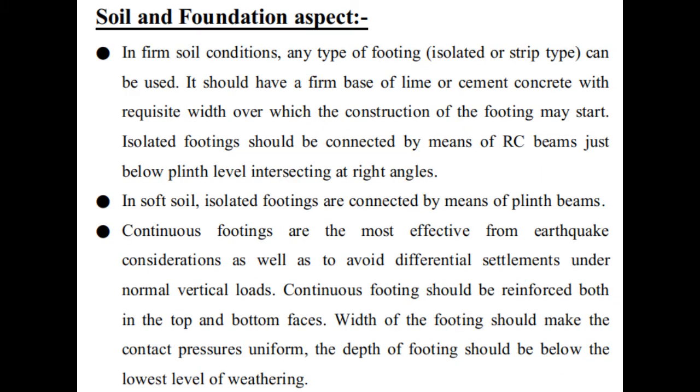Let us now see about the soil and the foundation aspect for the earthquake resistant structure. In firm soil condition, as I have discussed in my previous video also, any type of footing, isolated or strip type, can be used. It should have a firm base of lime or cement concrete with requisite width over which the construction of the footing may start. Isolated footing should be connected by means of RC beams just below the plinth level, intersecting at right angles at 90 degree.